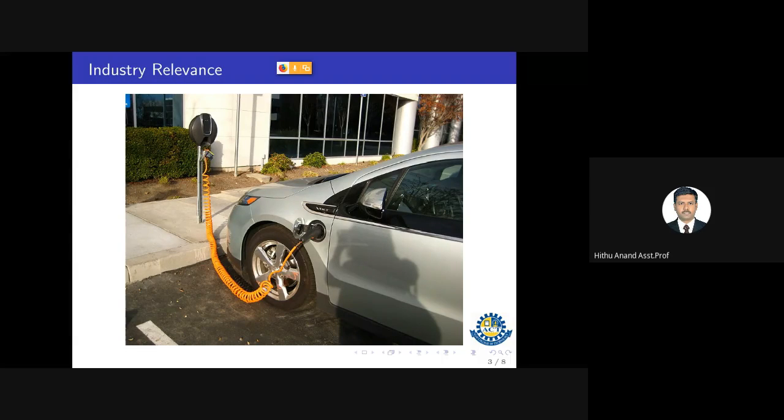That's the point. Now, assume you are going to design a drive for that. A drive, as I was telling, is a motor and load combination. So in this car, a BLDC, brushless DC motor, will be there, and there is going to be the car wheel. If you give an acceleration, what you are actually doing is increasing the speed of the motor. So you have to know the speed control methods. What are the speed control methods in the motor? That is one thing.